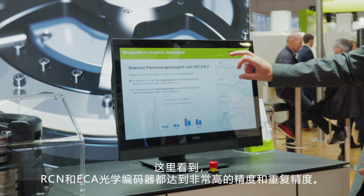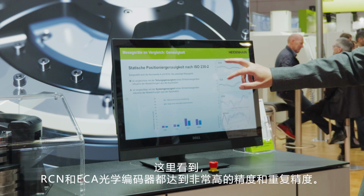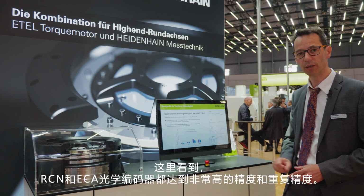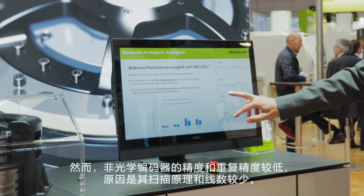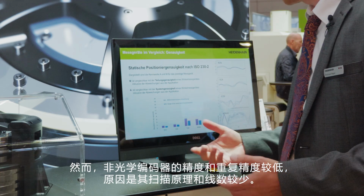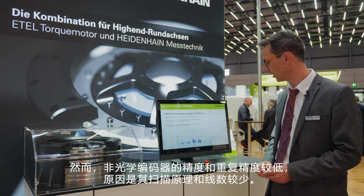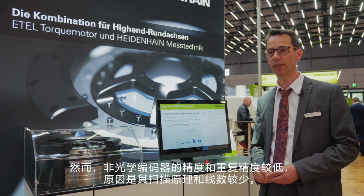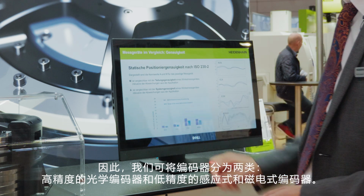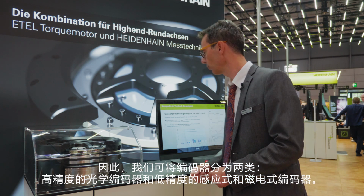Here we see the RCN and ECA optical encoders, which demonstrate very high accuracy and repeatability. However, these non-optical encoders exhibit lower accuracy and repeatability due to their scanning principle and lower line count. So again, we see 2 classes, the highly accurate optical encoders and the less accurate inductive and magnetic encoders.